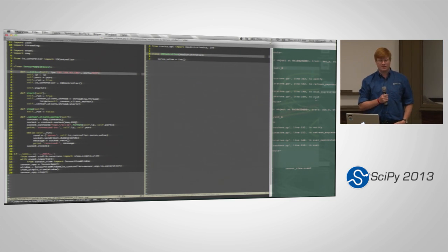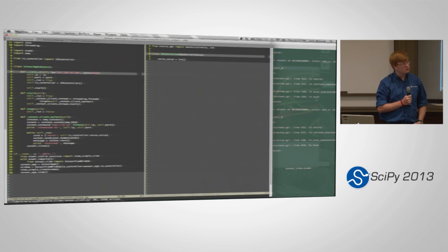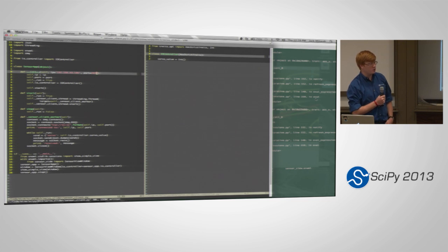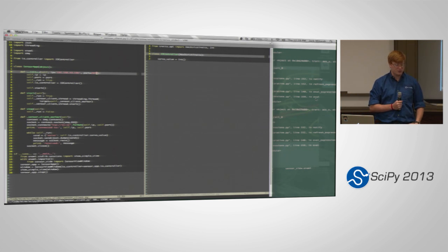Questions? Do you recommend Raspberry Pi or Arduino? So the question was, do I recommend Raspberry Pi or Arduino? If you want to do low-level servo control, the Arduino is certainly easier. You don't need kernel modules or anything. But if you want to do anything higher level, like streaming data over the wire, the Raspberry Pi makes that much simpler because it's a full Linux distribution. You have Python on it, and you can code in a comfortable language. You can actually use them both, have them both do what they're best at and communicate over serial to talk to and from. But really, it depends on your project, I guess.